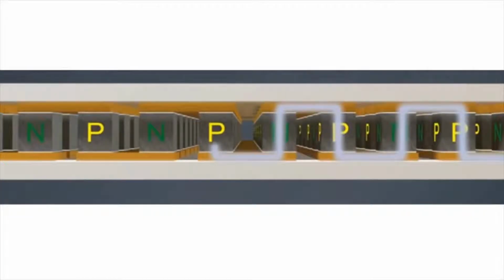This is a side view of the Peltier pad. When the current flows N to P, it creates a cold junction. This is because electrons are being removed from the surrounding surface. When current flows P to N, it creates a hot junction. The electrons that were removed from the cold junction are dispersed to the hot junction.